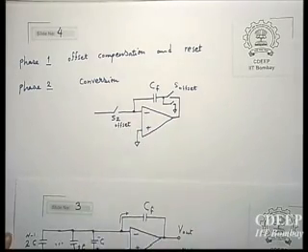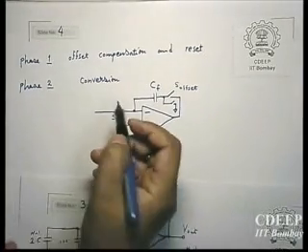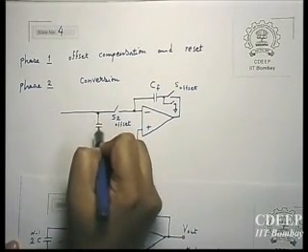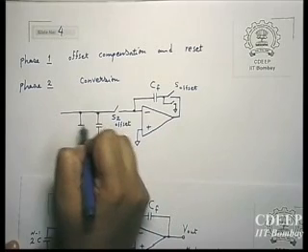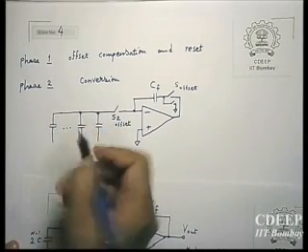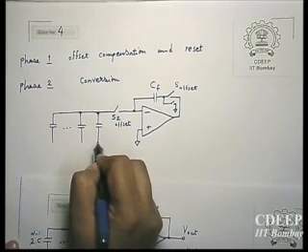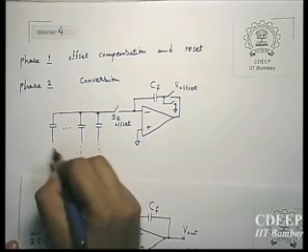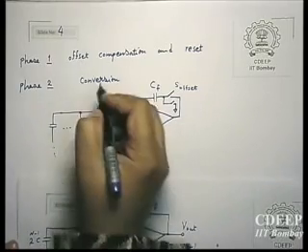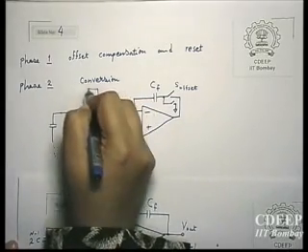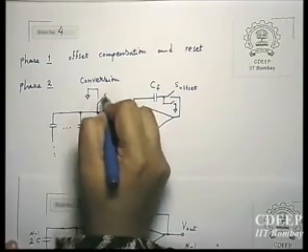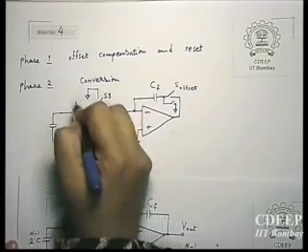I put offset because it shows that they are added because of offset. And then here was the capacitor array, binary weighted. Here are those switches. I don't redraw, you know what we are saying. I just want to show what has been added. And then finally you will have one switch over here to reset all capacitors. Therefore this is S3 for reset.